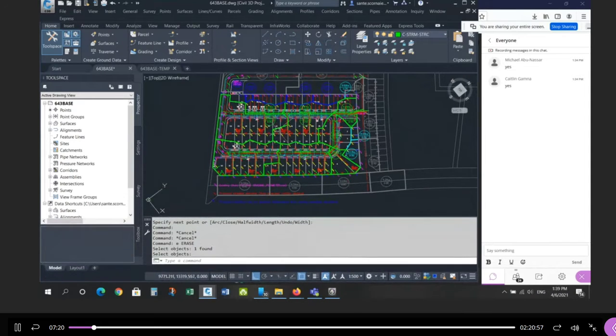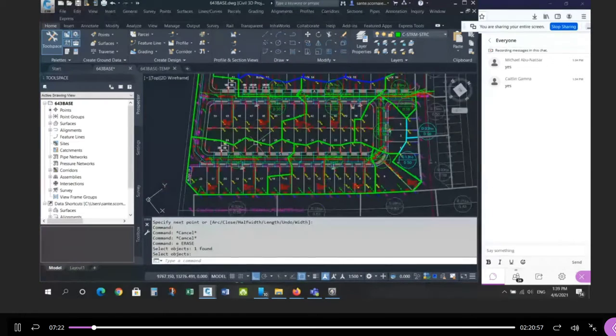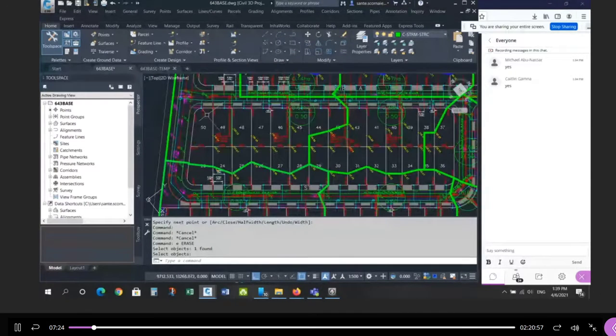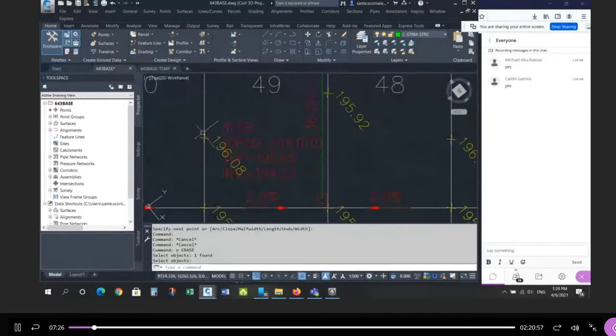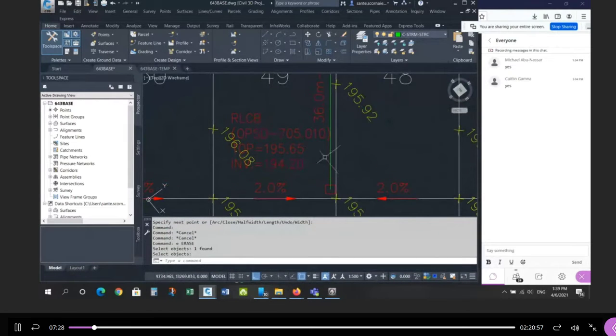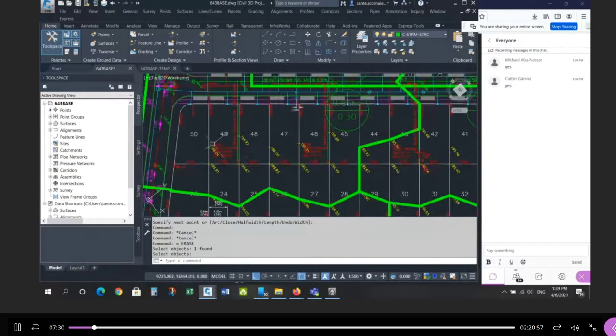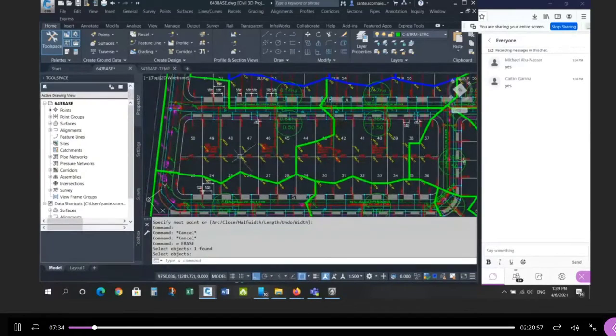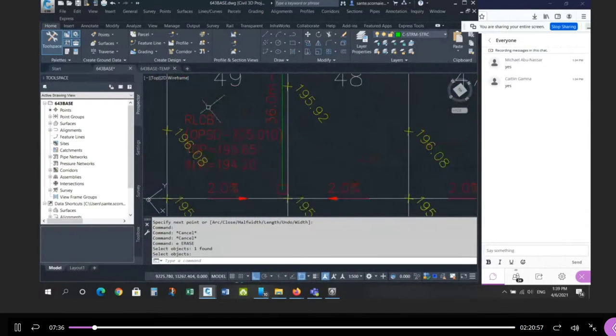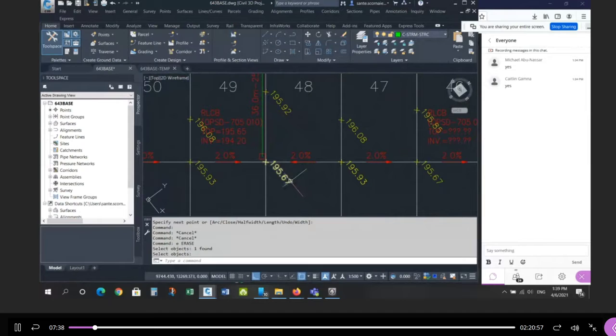The next thing we need to look at, and we did this before, I'll show you again. When I designed my sewer, and we did this together, remember? Let's do the calculation again. If you take the closest corner, I'm talking about just these 4 rear lot catch basins here, you find the closest corner elevation and subtract 2 centimeters, so the 567 becomes 565, and then we go down to the invert by subtracting cover and by subtracting the pipe size. Okay, so it looks like this.